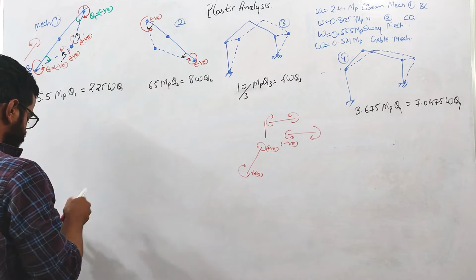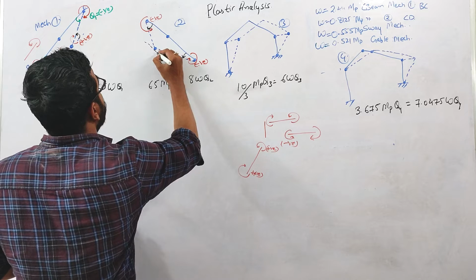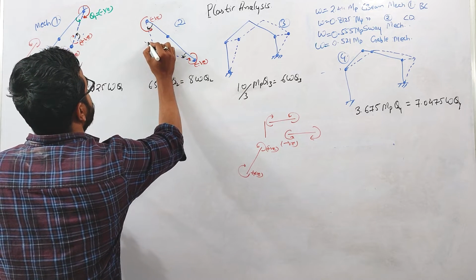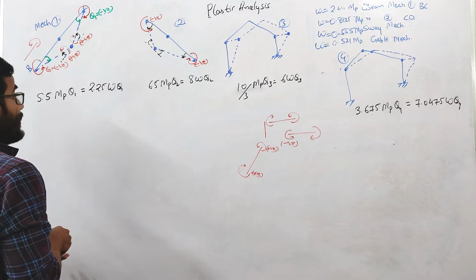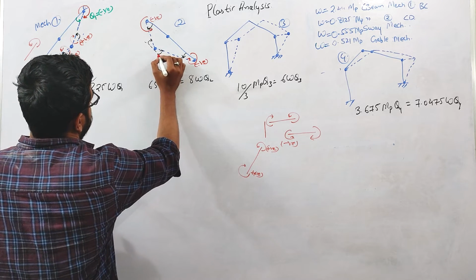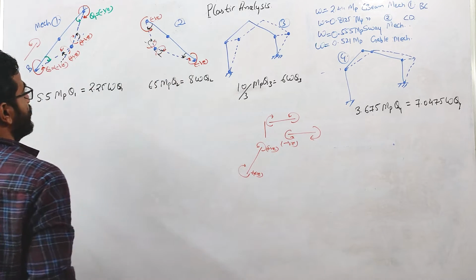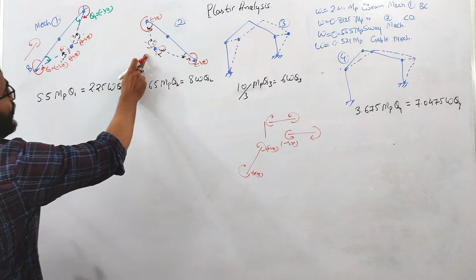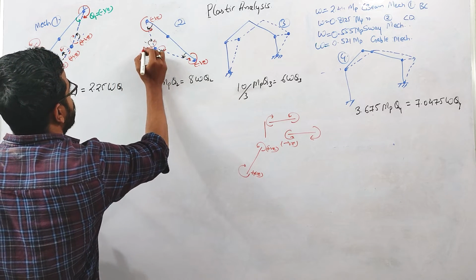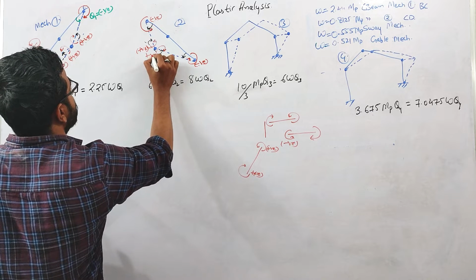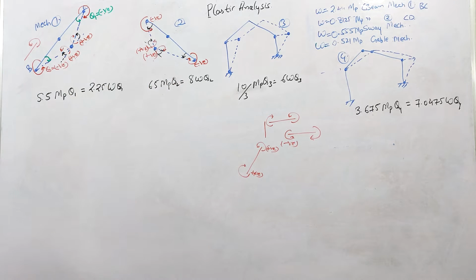Similarly here, this is the direction of the rotation. Here, this is the direction of the rotation. So here you can see that the direction of the rotation is in anti-clockwise. So the moment will act opposite to this, right? Similarly here, the moment will act in anti-clockwise direction. Okay. So this moment will produce compression outside, so this theta we will consider positive. This is positive, right? I hope this point is clear to you, because this is very important, how to decide what sign we should use at each rotation. Okay, because we are combining the mechanisms and it will be helpful to us.